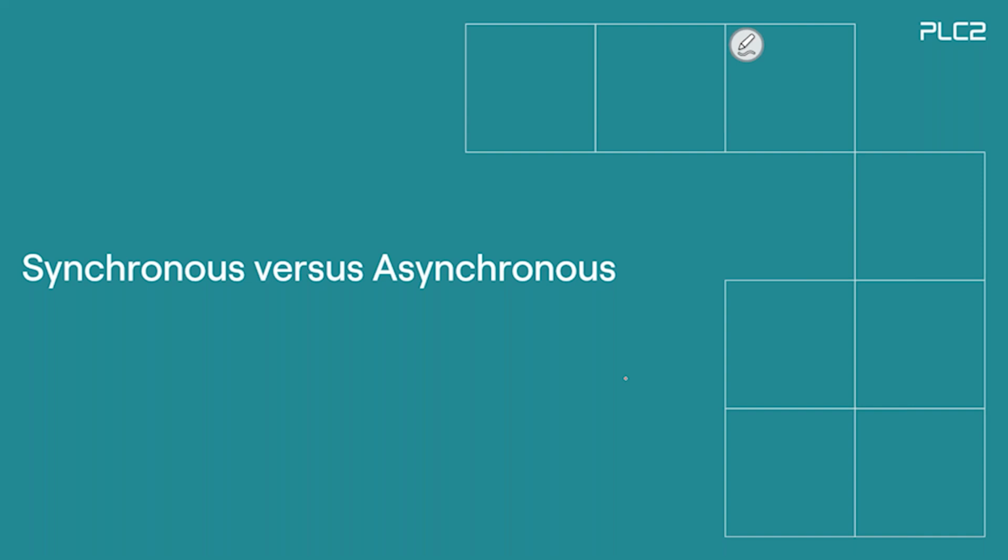But this is not really the last word, because in functional simulation we don't have any skews, any delay, or any strange phase relationship caused by delays. So it works, but this is not true for the real world.